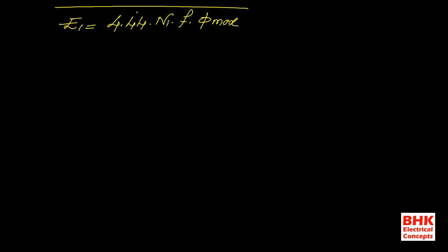Then E1 is equal to 4.44 into N1 into f into phi max. This is the EMF equation in the primary side of an ideal transformer.